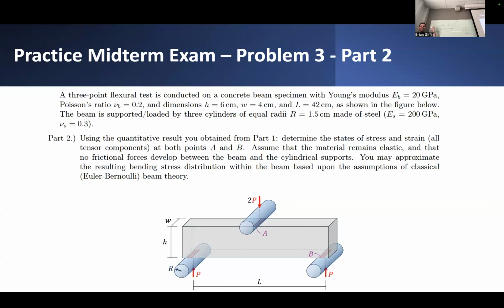So basically all of these different components of stress, at least on the front face and on the top face, except for the vertical stress, we can directly specify just by knowing what the boundary conditions are on this exterior point of the body. So that's the special thing. Anytime you're looking at this sort of edge of the domain, we can fully specify all these different components of stress.